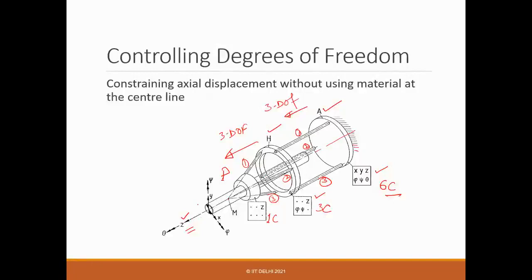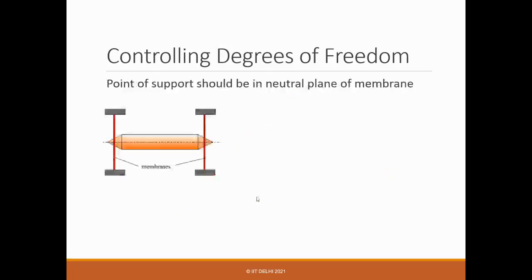So likewise, for any sensitive equipment or any device you are designing, suppose one piece you want to move back and forth, and you want to constrain it. So suppose P, this ring, is now completely constrained in one direction, and that is the translation. So this kind of design you can make using this constraint line concept or wire flexures.